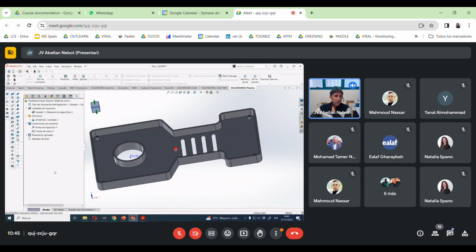In 95% of the situations it is shell that we have to use, because in plastics usually the parts are 3-4 millimeters thickness or something like that. So we should use shell study, and if you click shell study, probably then you will see this menu. Okay, so anyway, I'm going to give you the ideas about that, and then we will see any problem that you may have.